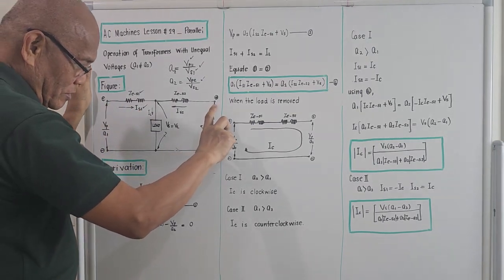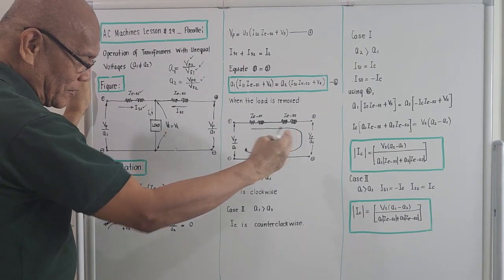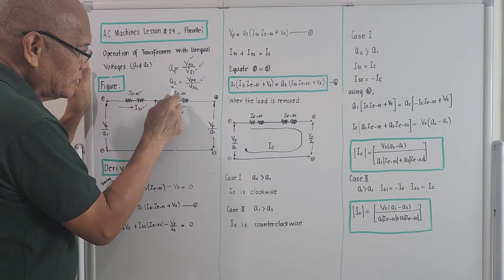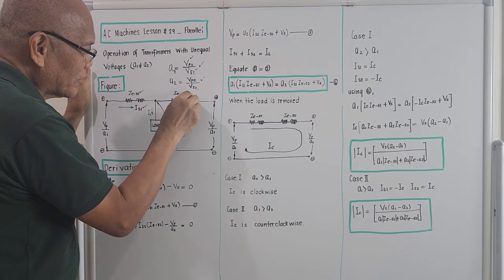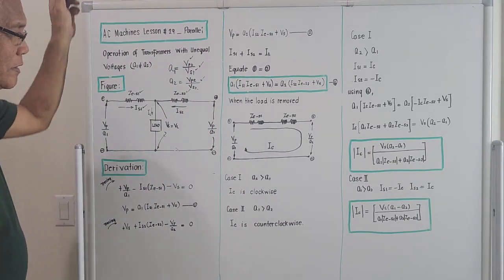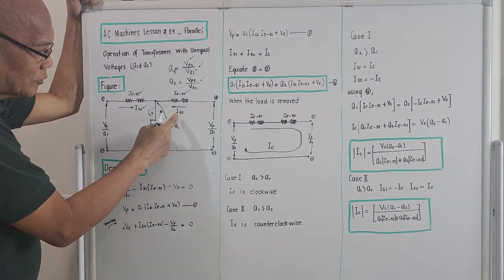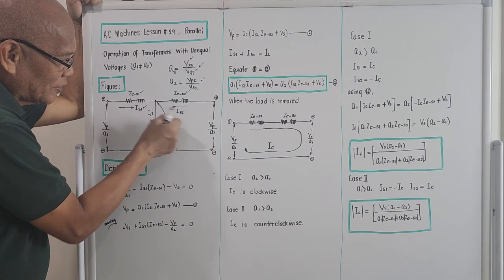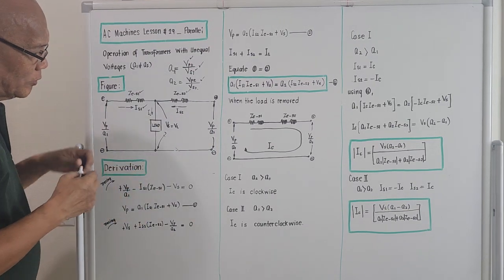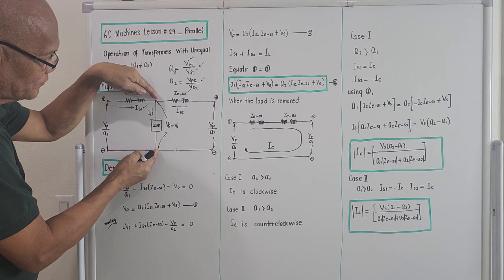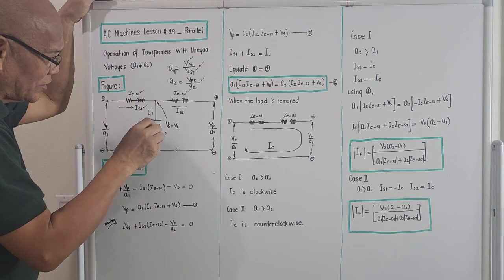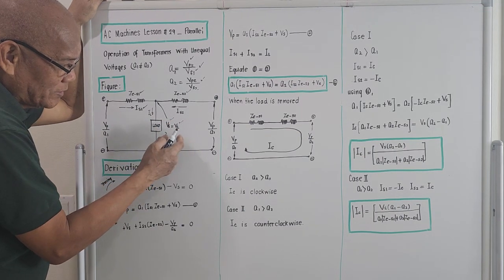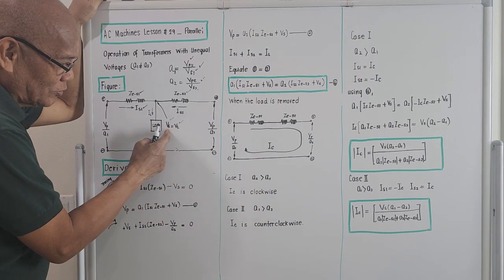The second transformer will have the input voltage coming from the primary side, VP over A2, and it has an impedance of ZeS2. So this 2 here refers to transformer number 2. The current given by this transformer is designated IS2, meaning the secondary current given by transformer number 2. And the voltage across the load is VS, the secondary voltage, which is equal to the load voltage, VL. This is the one that goes to our houses.